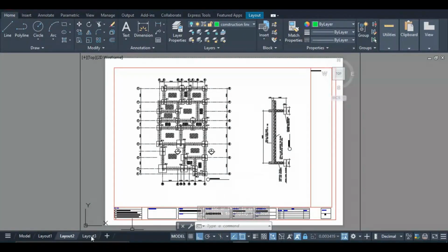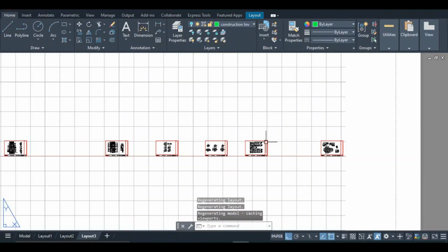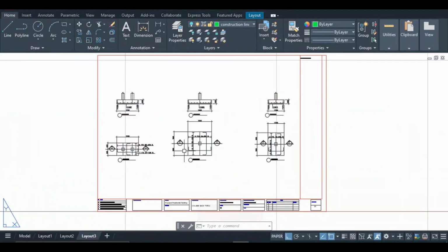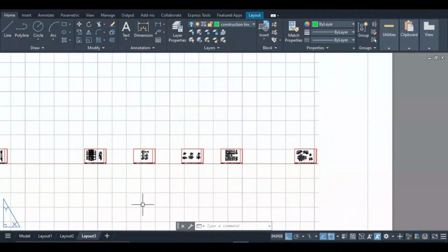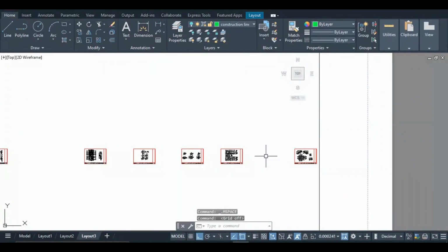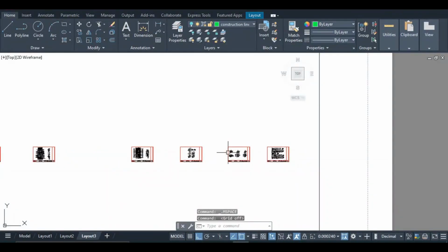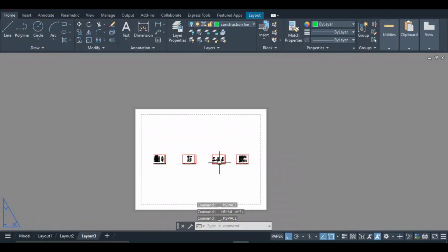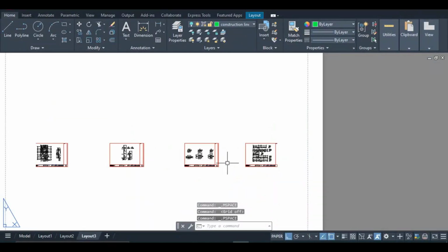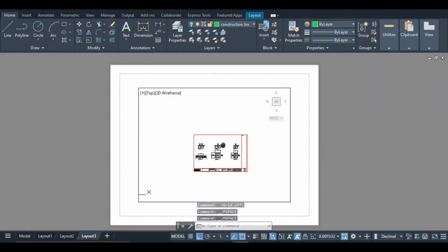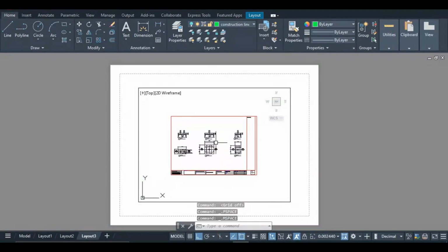Now I always love to lock this. So let me go to layer 3 and choose another random drawing. Let's choose something like this. But first and foremost, remember how we go about it. We remove the grid. We don't want our grid to be plotted. So I need to go back to paper to be able to zoom this out, then I'll go to model space and single this one out. Understand?